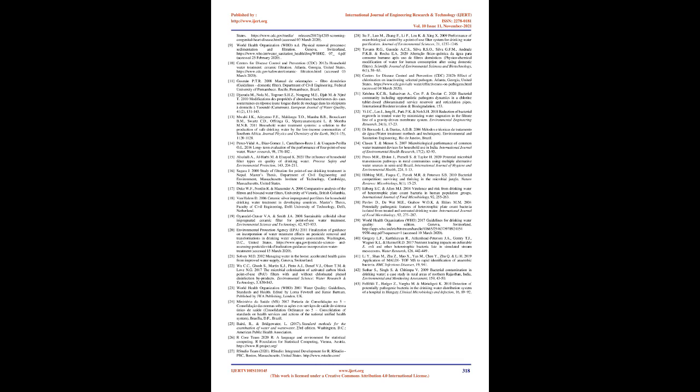It is relevant to mention that the lowest count of heterotrophic bacteria was observed in C3, not detected in 100 ml of sample, showing that an adequate storage of non-filtered but well-disinfected water source, presenting a relatively high level of free chlorine, 0.80 mg/L, can be more adequate than its storage following any POU water treatment tested in this research, independently of the ceramic candle type.